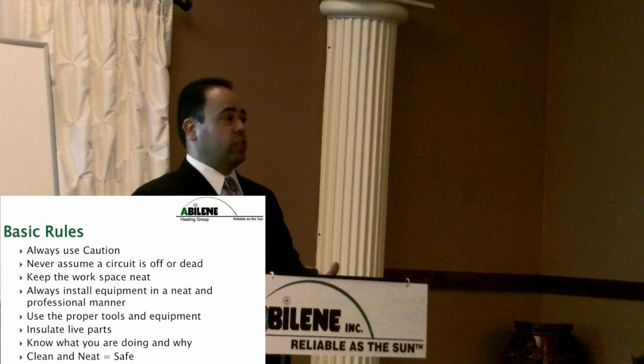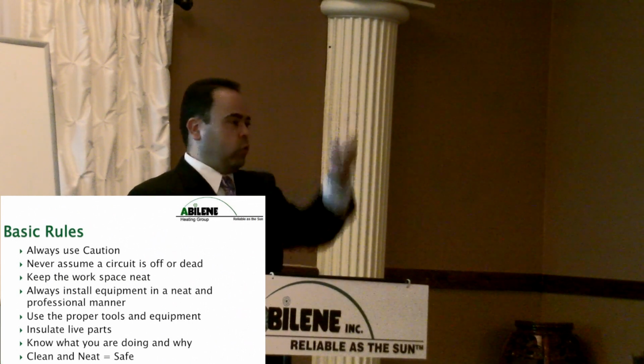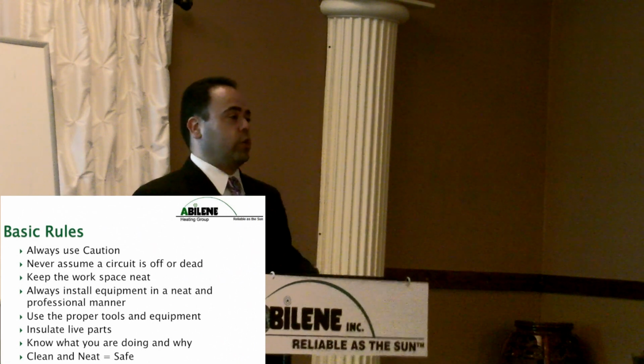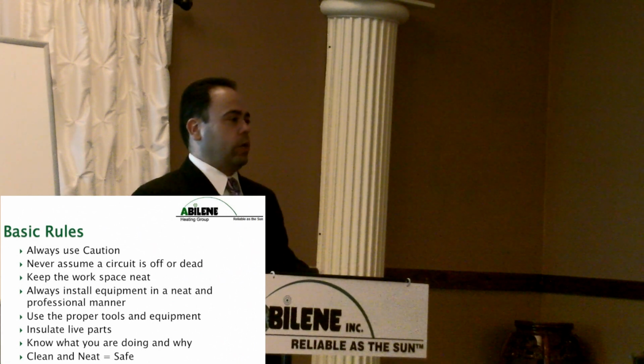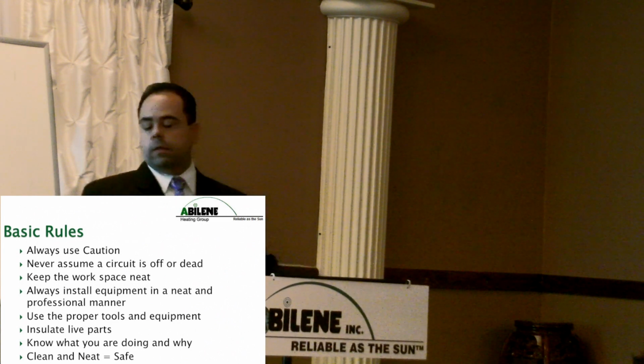We exercise the limits. We exercise the low water cutoff. We drain the low water cutoff, make sure the water comes out of it, make sure the burner shuts off. Now I know it's wired in series. Okay? Everybody get that? Okay.